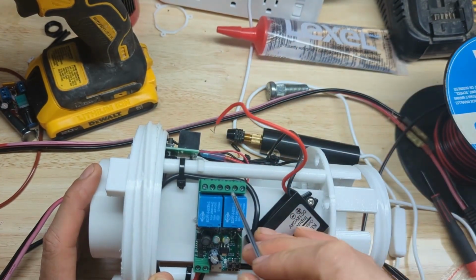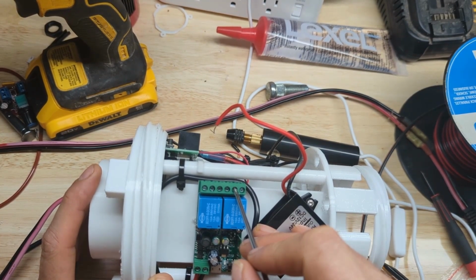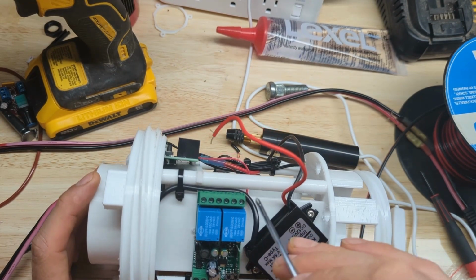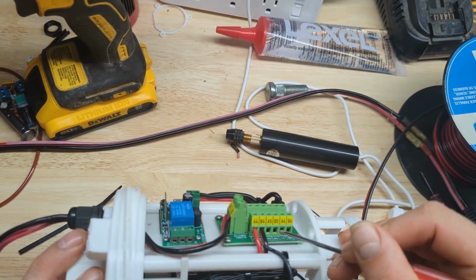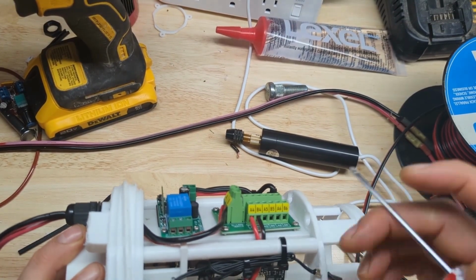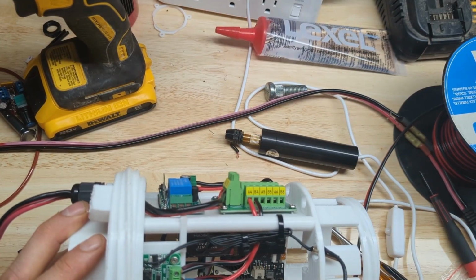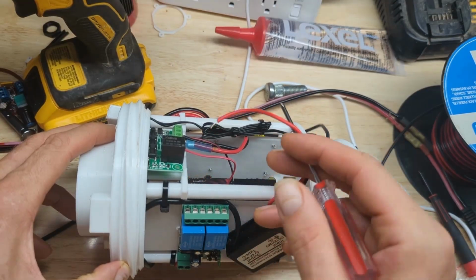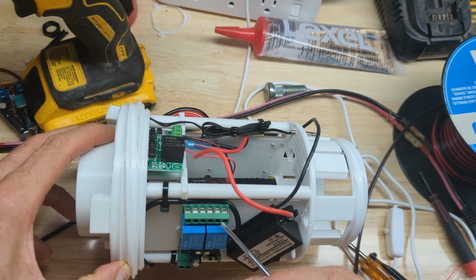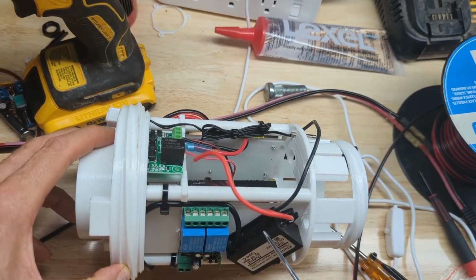Now the second screw, we don't use the third screw at all. The second screw, we wire that directly into our power block. So we will take a wire, run it all the way over, and connect it into either A5 or A6, depending on where we hook this negative up at. So basically, the second port, you need to provide a constant power source to this block. So whenever this relay switches on or off, it takes the power from that block and basically transfers it over to this little slot here. So it's got power coming out of it, provides power.